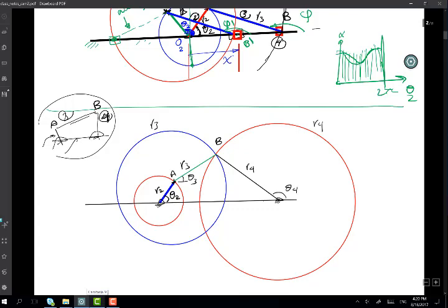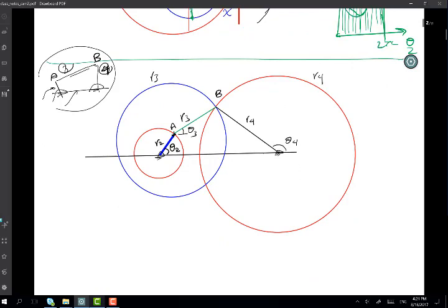All right, and then you draw this to scale, and then you measure the values of your angles theta 3 and theta 4. If the position of point B is also required, you just measure the position. So you have to do this to scale to be able to say I've done a graphical solution, right? Without that, the values you measured will not be accurate.